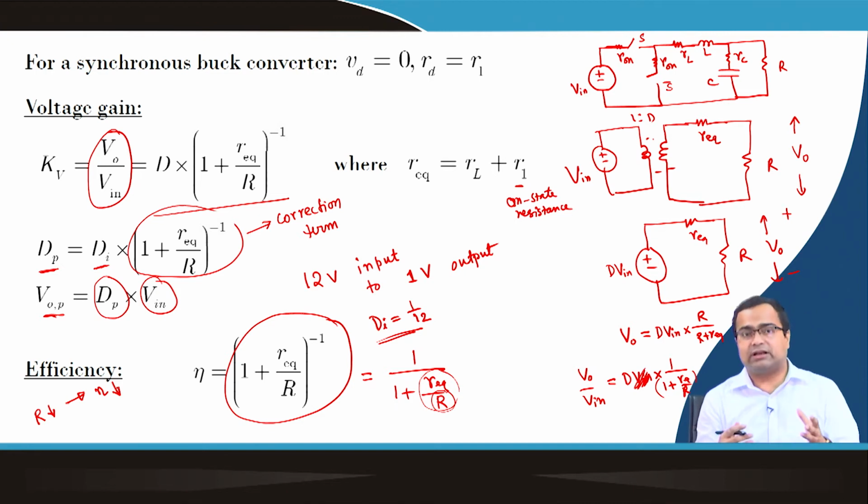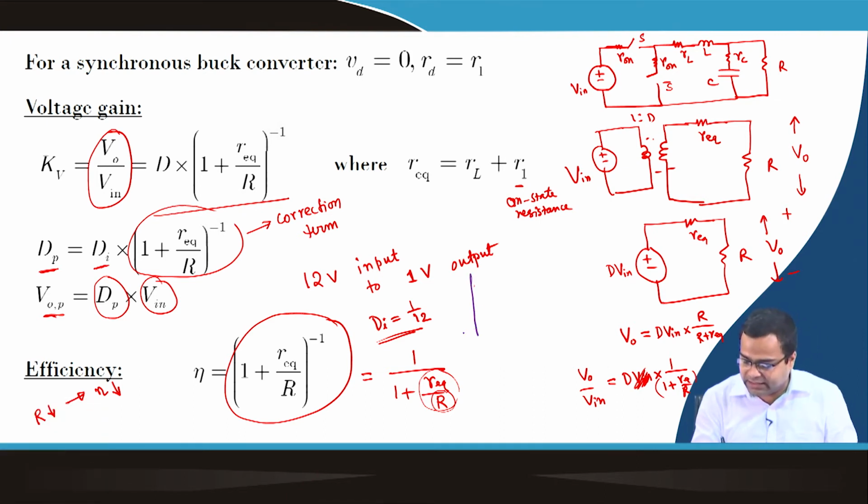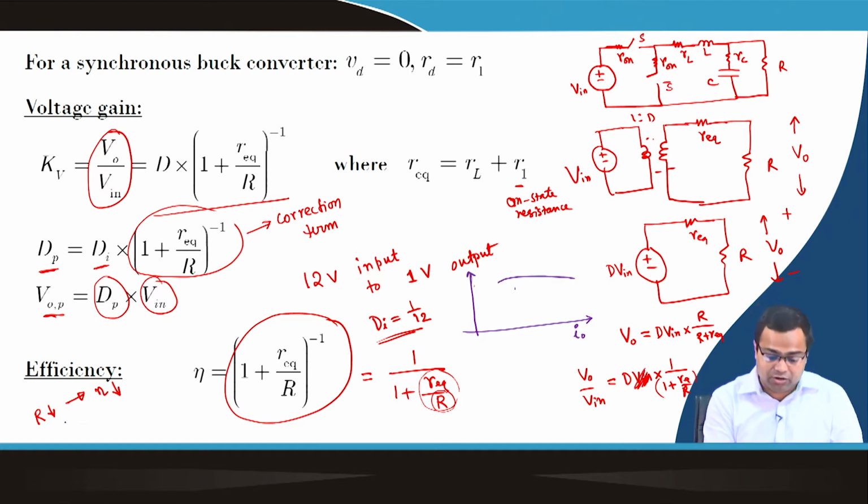That is why we have discussed earlier that if we plot load current under continuous conduction mode, it will decrease, because this is due to the conduction loss, which can be modeled by this equivalent resistance. But this is a DC term, we have not incorporated the ripple current, only the DC term. So for accurate loss we need to go for RMS current calculation and all, but this is just the DC equivalent.